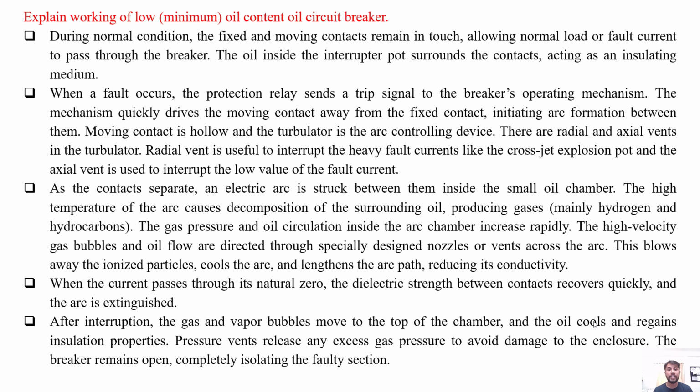Now, when the current passes through its natural current zero instant, the dielectric strength between the contacts recovers rapidly and the arc is extinguished. After the interruption, the gas and vapor bubbles move to the top chamber and the oil cools and regains its insulation properties again.